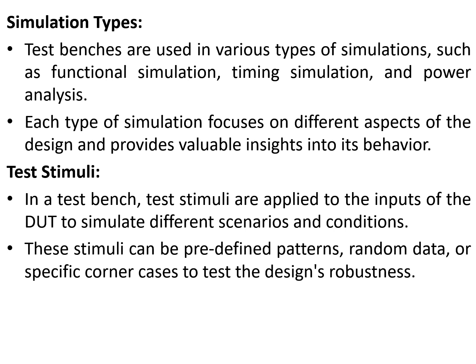Test stimuli. In a test bench, the test stimuli are applied to the inputs of the design under test to simulate different scenarios and conditions. These stimuli can be predefined patterns, random data, or specific corner cases to test the design's robustness.